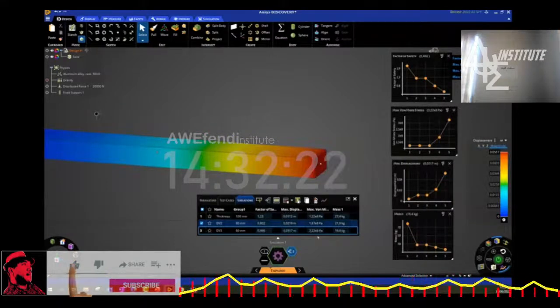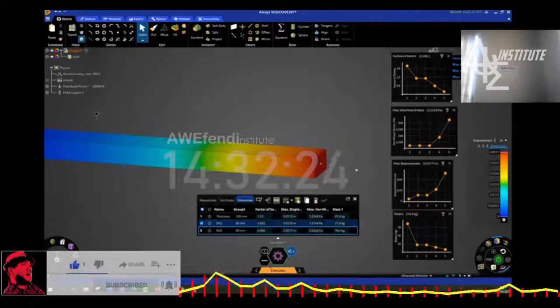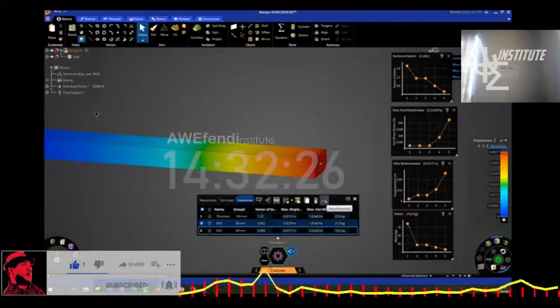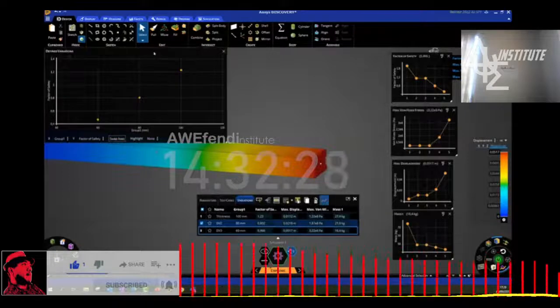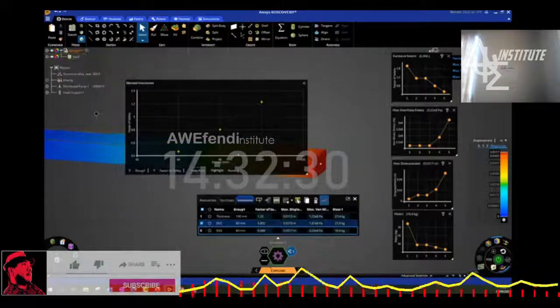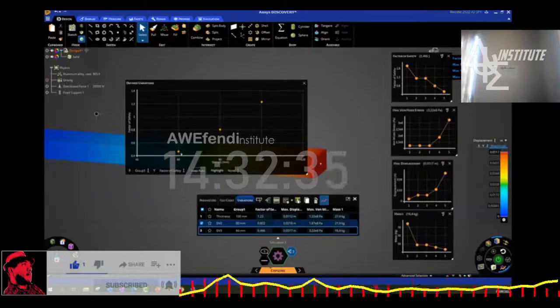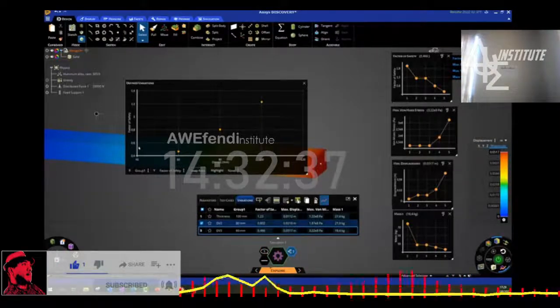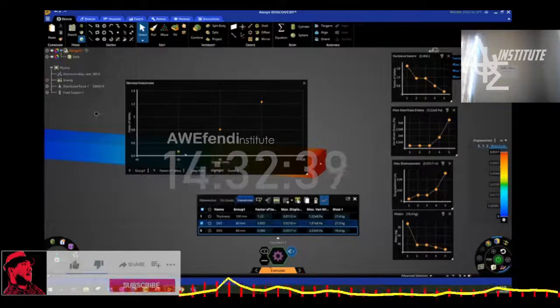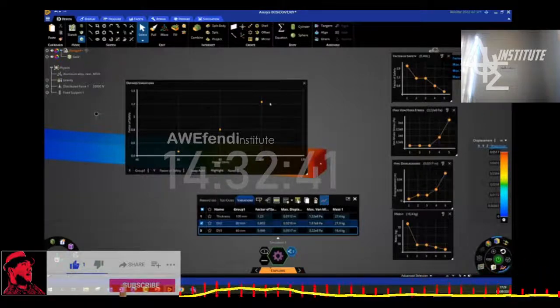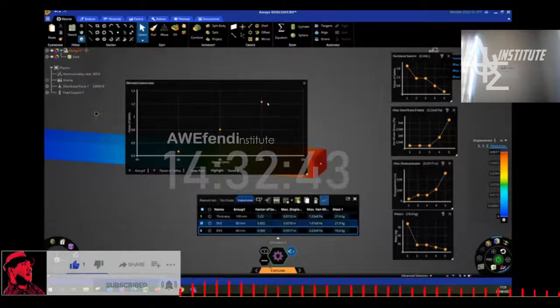Okay. Now the simulation has run, and what we can do is visualize this in the form of a graph over here. We can see that the model is validated over here. We can see that at 60 millimeters, the factor of safety is below 0.6. And as the thickness increases, the factor of safety also increases, which makes sense.